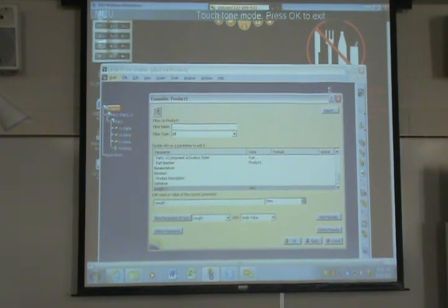Did that name come up automatically? Yeah, length.1 is the default. Okay, it did not do that when I was checking it out. So you just click on it and say length. I think the average length of a skeleton for an RC car is about 350, 360 millimeters, somewhere in there. So I'll make a guess and say 350.